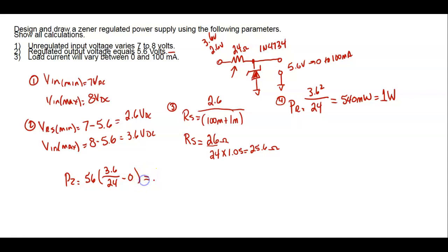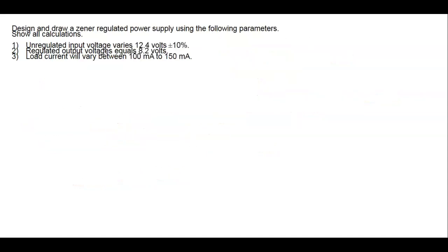So what's the power in our zener? I think this is going to be dangerous, right? Okay, we squeezed it in. Yeah, because it's a 1 watt zener. We're right under the limits. Yeah, all these zeners are 1 watt zeners. That's it. I don't think there's another version. The thing to do is probably just rework these and then verify that you worked them right.